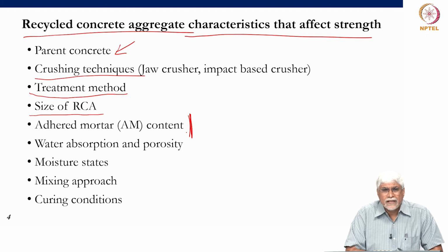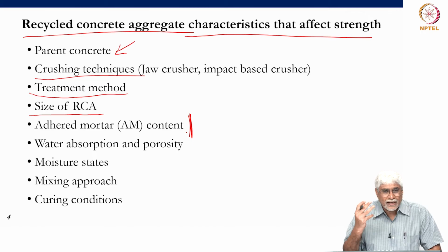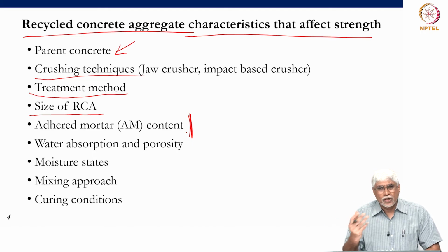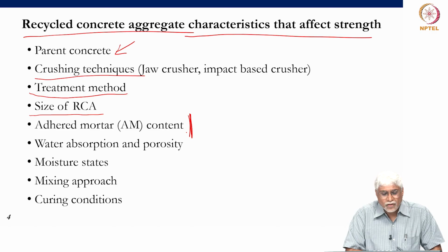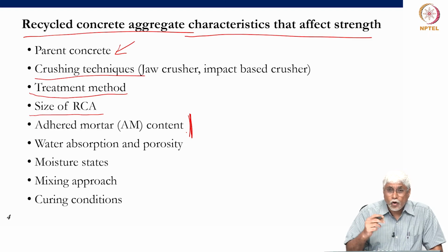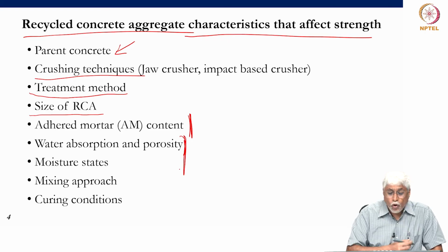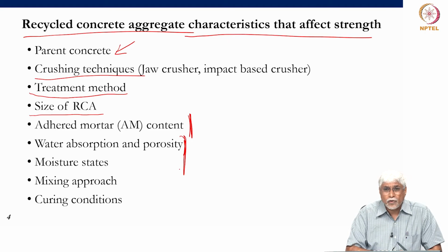So, the strength and durability really is affected by the adhered mortar, and that is something that is always a concern. If there is no adhered mortar and we have the same aggregate as before, then we do not have to worry about anything at all. We can talk about this new concrete as good as the original concrete. The adhered mortar content, how much is still left, matters. The water absorption, which indicates the porosity, how much water is going to be taken up by the aggregates when we put them into concrete, matters.